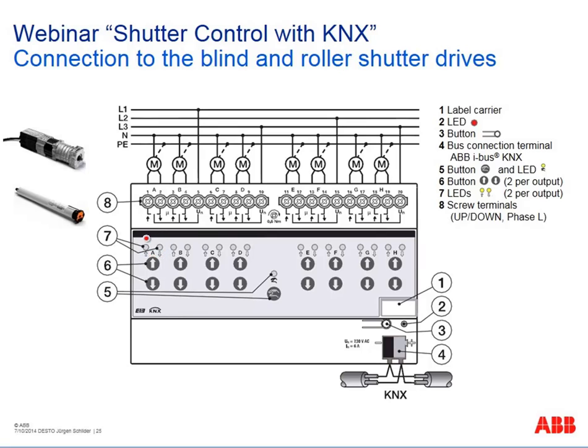If there's any security function active, we come to this later, both LEDs will be on here for 1 channel, showing you that a normal operation is not possible. If you press this button again, you go back to the standard bus mode and no manual operation is available anymore. So back to the hardware here, we have a changeover contact.